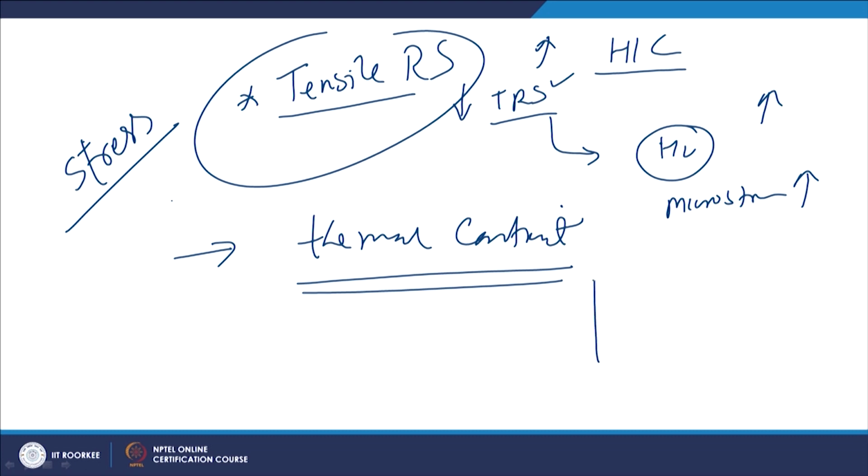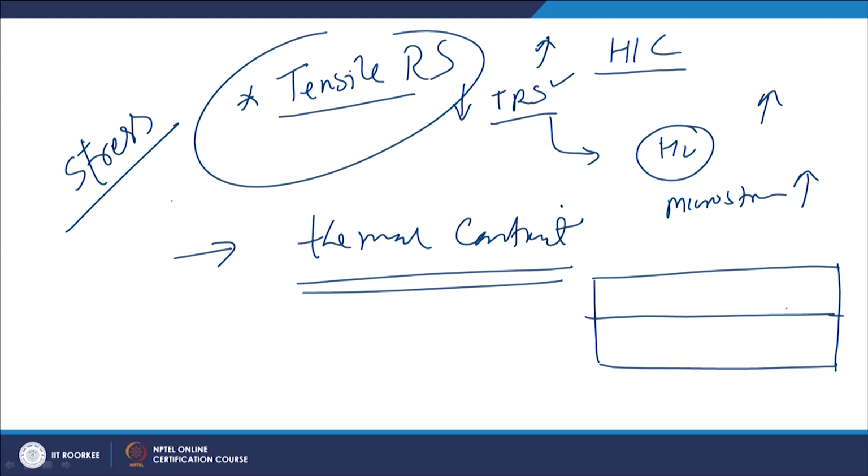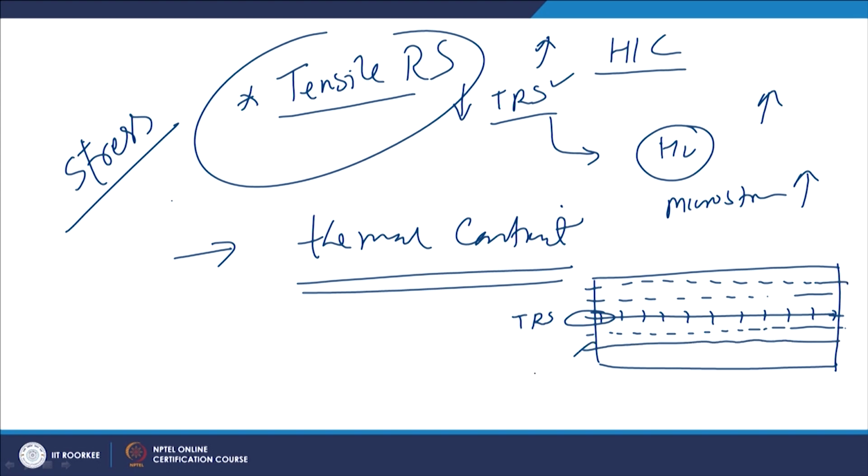So, wherever the maximum contraction is restricted, that restriction is observed in the weld zone. So, this experiences the maximum tensile residual stress, while the zone in the vicinity of the weld metal will also have some amount of tensile residual stresses, and thereafter the balancing residual stresses are also developed on both sides of the weld metal, and these will be in the form of compressive residual stresses.